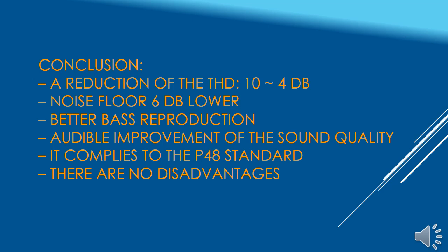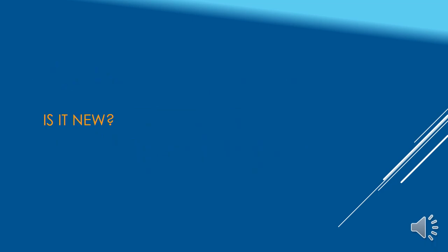Conclusion: reduction of the THD, for low volume 10 dB, for higher volumes 4 dB, noise floor better, better bass reproduction, audio improvement of the sound quality is good to hear. It complies to the standard, and there are no disadvantages. Is it new? Yes. The patent has been granted.